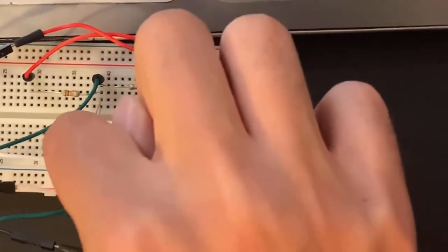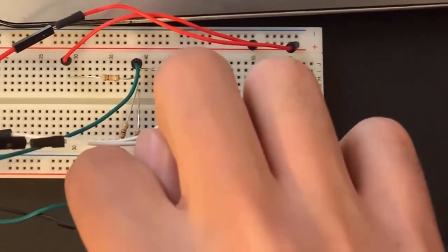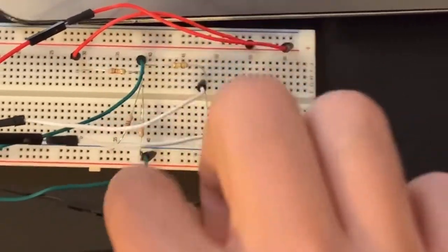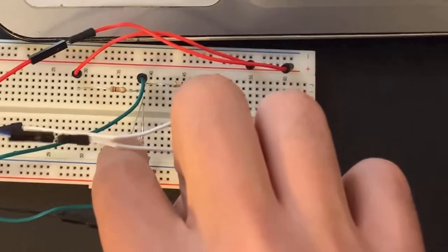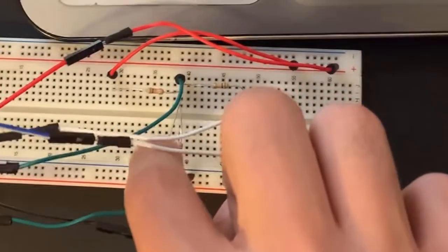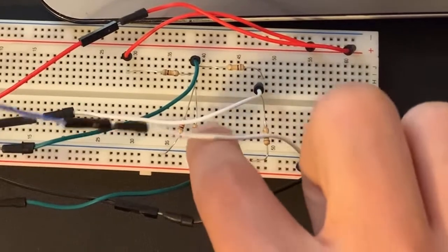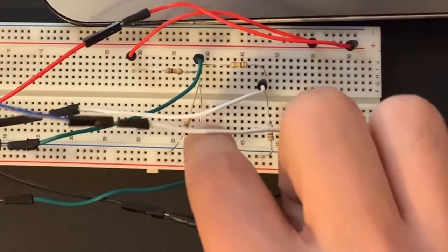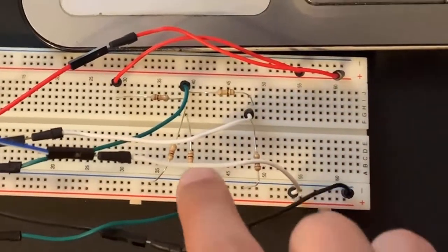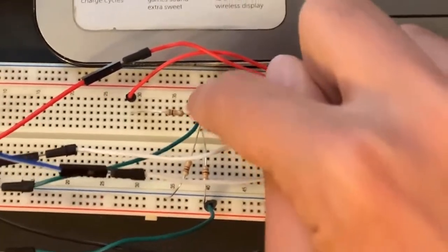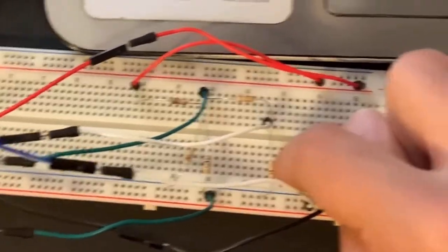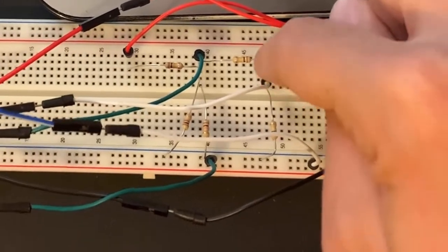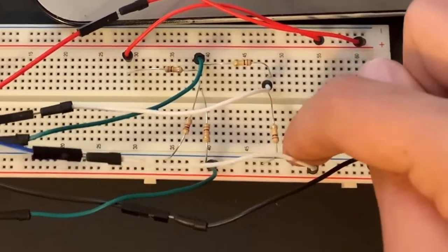To calculate the current flowing through this resistance, it will be V1 minus 0, which is the ground voltage, so we are focusing on the drop over the resistance. So it's V1 minus 0 over the value of the resistance, which is equal to 0.416 milliamperes. For the other one, it's the same voltage, V1, over the value of the other resistor, which is 10K, so it will be 0.0416 milliamperes. And finally, the current flowing here, I3, you can find by dividing the voltage across this resistance, R5, over the value of R5.